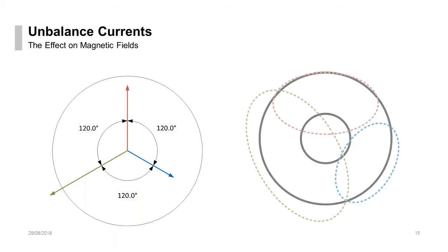And we'll do the exact same exercise, but looking at the current or the magnetic fields as a result of the current. And again, our magnetic field is no longer centered on our rotor. Instead, it could actually shift all the way over into the stator. This is where you start to see a lot of the interesting things like bearing fluting and some of the other manifestations that are really typical in improperly set up VFD systems. It's by creating this non-zero vector sum, where we're shifting magnetic fields, that creates a potential between the rotor and the stator. So the only way to fix this is to clean up the power.